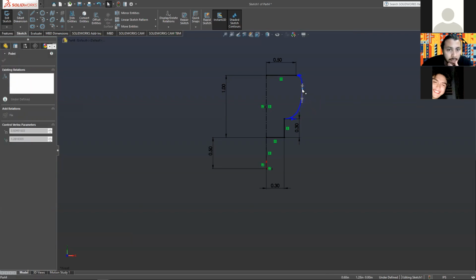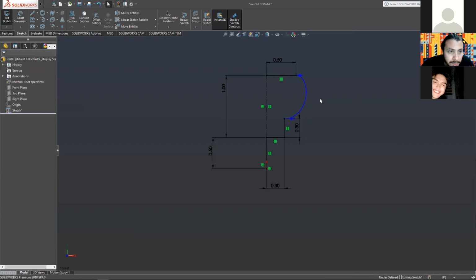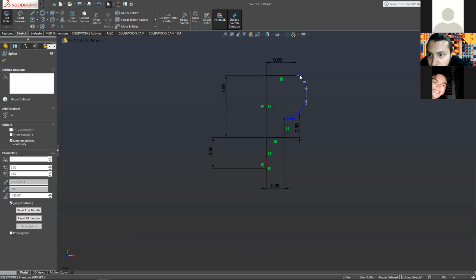Edit sketch. We did that here. Can you repeat how to get that angle again? So you gotta select the little arrow, come down here and make sure tangent driving is checked. Tangent driving is... oh, there it is. Okay, yeah, we hit that 0, right?